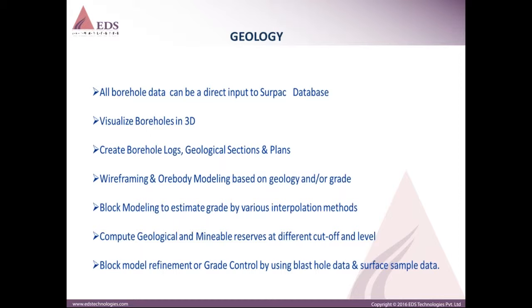And then you can do block modeling to estimate your grade by various interpolation methods. We have inverse square distance, ordinary kriging, and simple kriging as various interpolation methods. And you can compute your geological and mineable reserves at different cutoff levels. And the block model refinement: once the block model has been created, you can refine your block model during the mining operation. So this will be useful. This block model refinement is mainly done in the mining industry, where we are currently mining the resources.